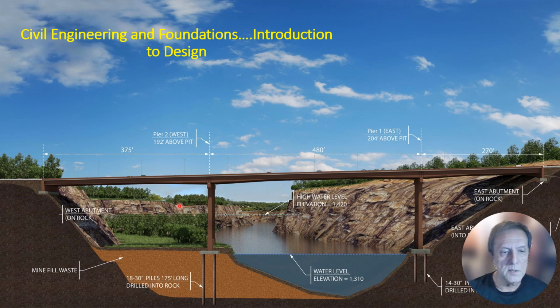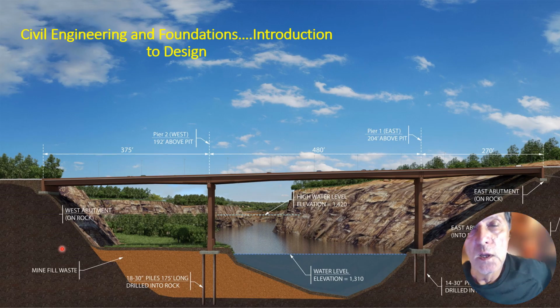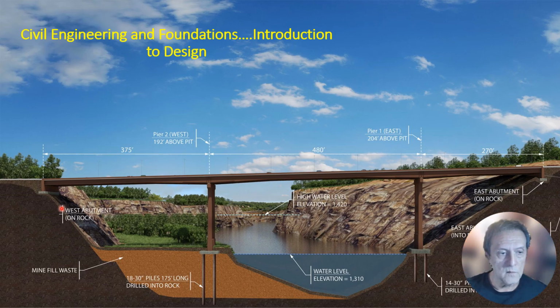And as you might be able to see right away, there are different foundation conditions. Foundation is one of the crucial structures, of course, in building a stable structure. And you have to have a foundation that's suitable for ground conditions. In the west abutment, we have very stable bedrock, so we can put that concrete foundation or footing right onto that stable bedrock. Move to the right, and you see there's a pile of waste material from mining.